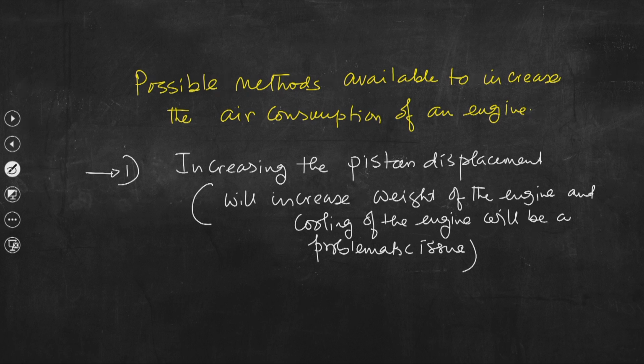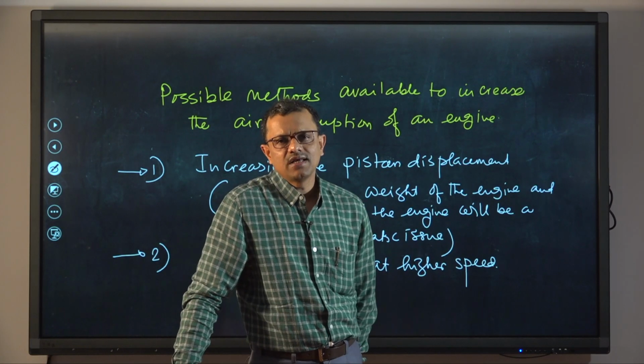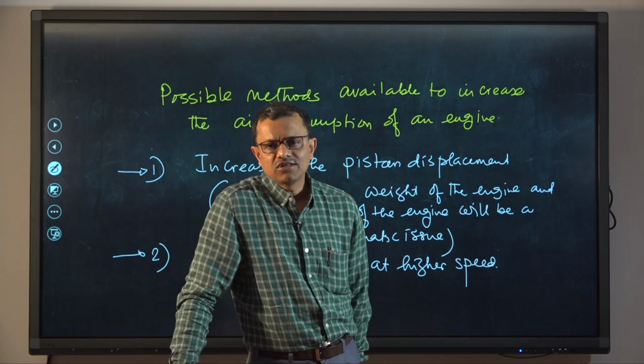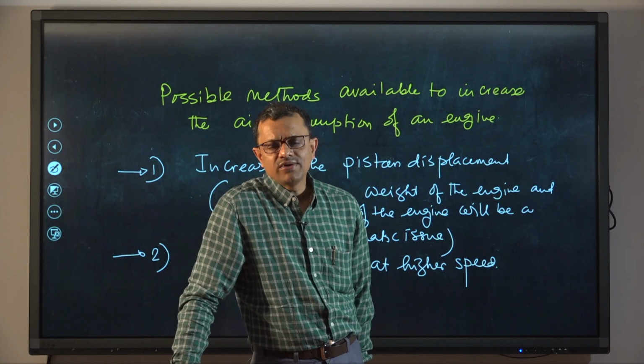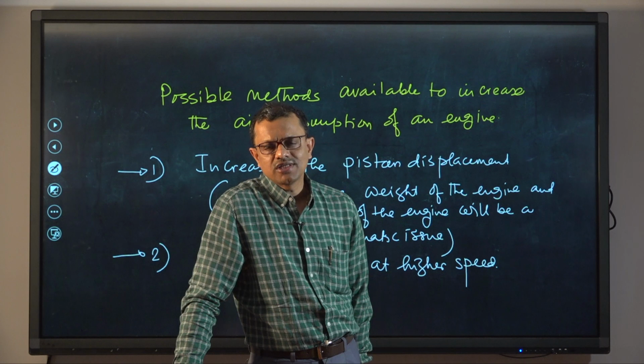Okay. Then the second option could be running the engine at higher speed. So this could also be an option to increase air consumption of an engine, but if we allow the engine to run at a higher speed, then certainly frictional losses will be more.